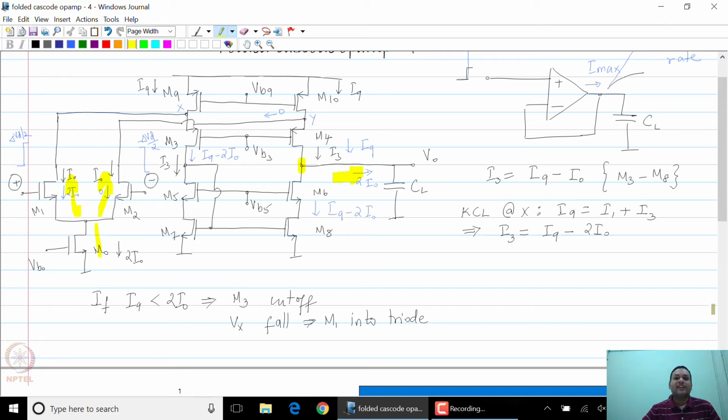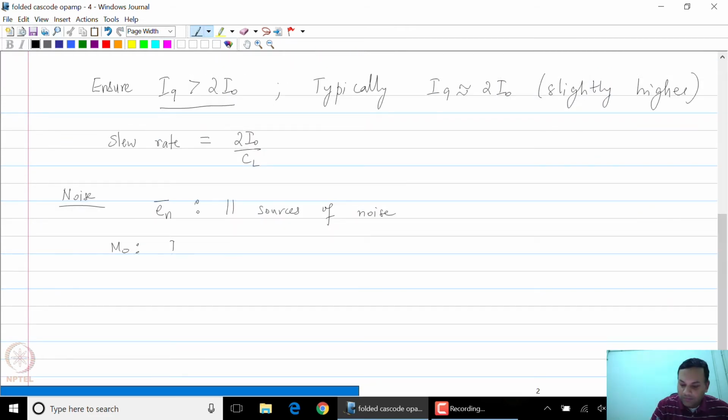As always, you can either short circuit the output and look at the output noise short circuit current and divide by the transconductance of the op amp, or you could look at it at no load condition and divide by the voltage gain to get the input referred noise voltage. Either one of these will give you the same answer. So noise of M0 goes through identical paths, especially at low frequencies, and therefore gets cancelled. You assume that the two paths are identical.